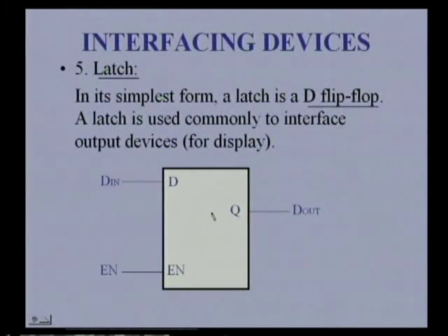And these are common interfacing devices, and you can see these are hardwired, non-programmable devices. The functions of these devices are fixed, we cannot alter them. There are other types of interfacing devices called programmable interfacing devices. With these, by writing some control word into their control register, we can alter the function of the circuit too. Let us see them.